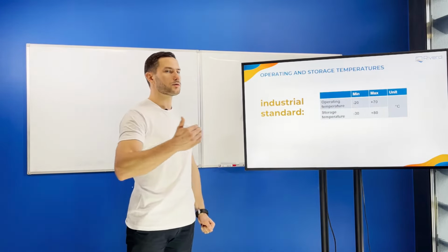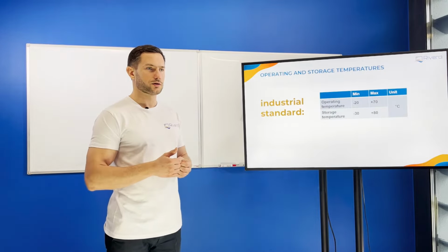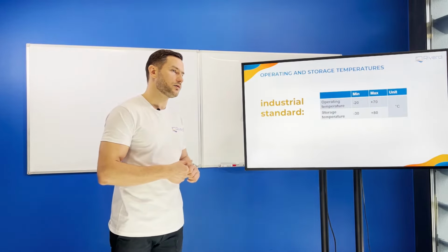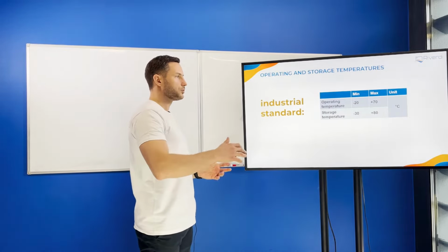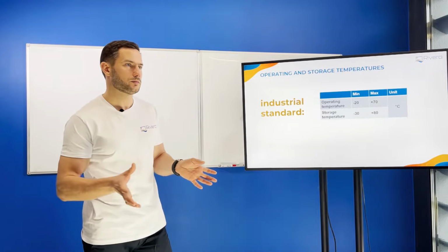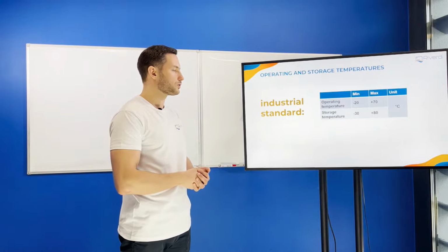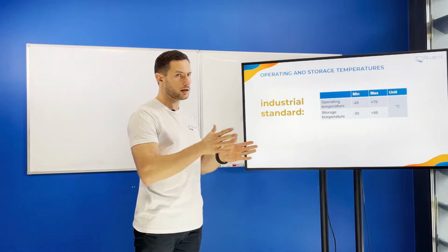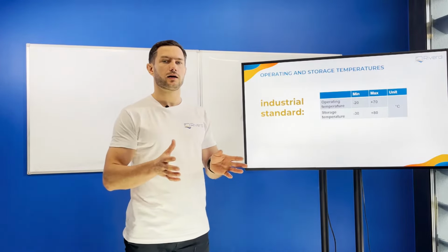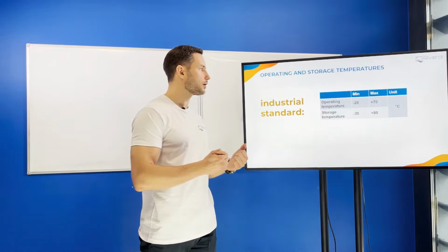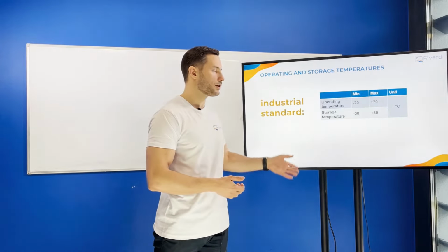But for a real outdoor LCD, it's too low. It's too low on two ends. So -20 in many cases is not enough. Maybe -30, -40 would be good enough to have an outdoor display worldwide. Maybe in Scandinavia or somewhere else, we may expect lower temperatures than -20. And on the high end, it's also a problem because if we are outdoors in the summer with direct sunlight, the surface of a display can go higher than even 70 or 80 degrees.